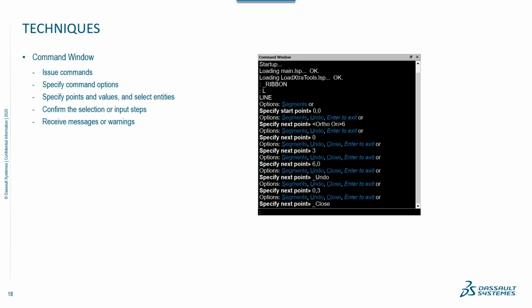When I drew that sketch that I showed you earlier, I started at 0, 0 and added a line. One thing I want to point out in particular is ortho mode, orthogonal. There's a shortcut, the F8 key, and it constrains your lines to 90-degree increments, so they're either horizontal or vertical.